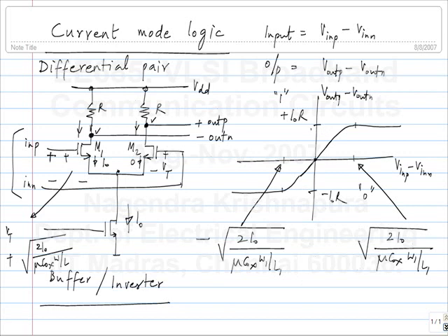The spacing, this vertical spacing, will be the input to some other logic gate, and that should definitely be more than this one. Because when it's operating as a logic gate, we want it to operate in this region and in this region, not here. So anything that we say is an acceptable one, that should be here.